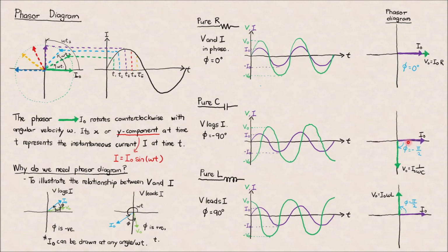If you try to measure the phase angle, it is again the angle of V0 with respect to I0. So the angle should be measured from I0 to V0. From I0 to V0, we see that it's a clockwise angle. In that case, it's opposite to our natural rotation, which is anti-clockwise. Therefore, the phase angle should be negative pi/2.